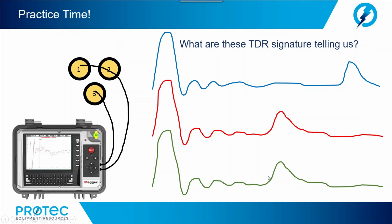Our conclusion is that there is an open on conductor 3. We know the open is not on conductor 2 because when we looked from conductor 1 to 2, we had beautiful continuity and saw to the end termination. The open circuit only shows up when conductor 3 is part of our connection.